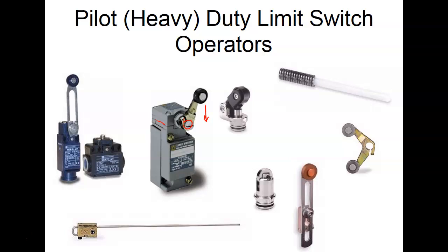we got several of these, and you can actually look at the contacts inside these. They got a lever system inside there, so when it hits a plateau, it switches real fast. Why do we want contacts to switch real fast? So they won't arc and weld together, right? Are we okay?